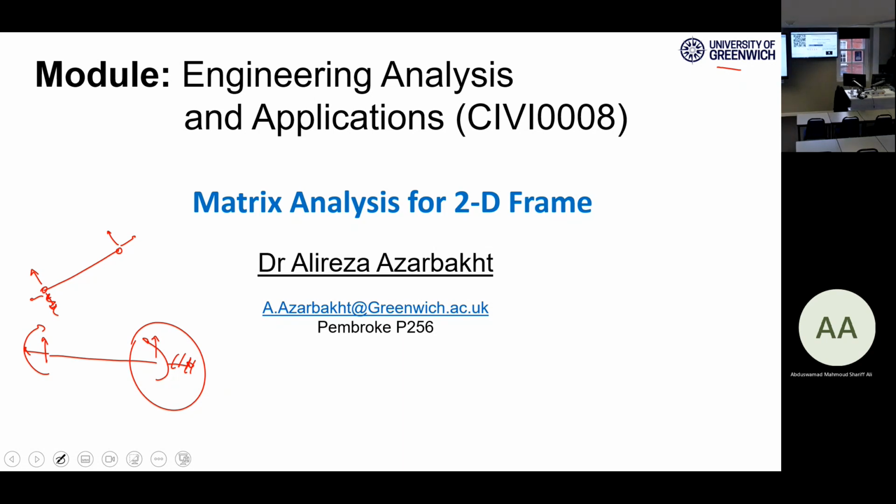It's somehow like truss structures, but the difference is these 2 are translational deformations, but this is one translational and one rotational deformation. All right. In the beams, one node can go up and down perpendicular to the line of the element and can rotate. So you have a translational deformation and a theta, a rotational deformation, right? Again, if you have a structure with 5 nodes, you can just count the nodes and multiply by 2 and say, okay, we have a 10 by 10 matrix when we are going to work with this example, right?